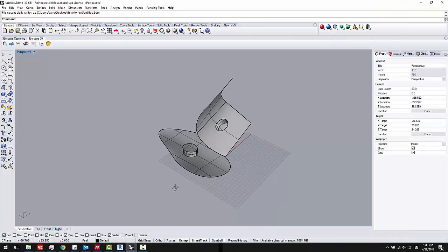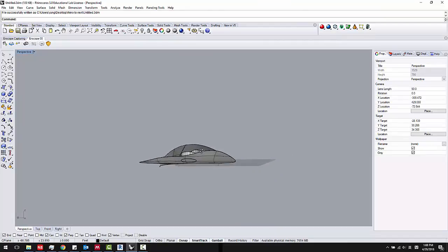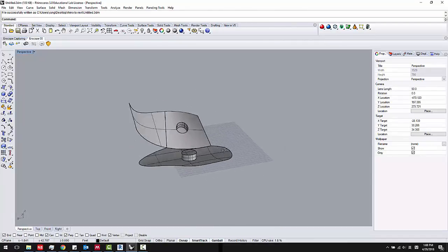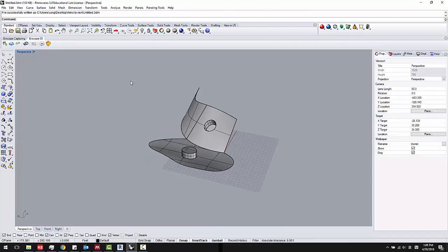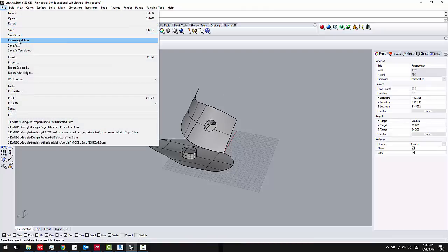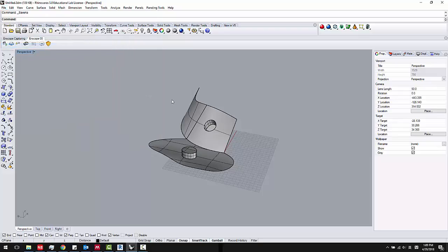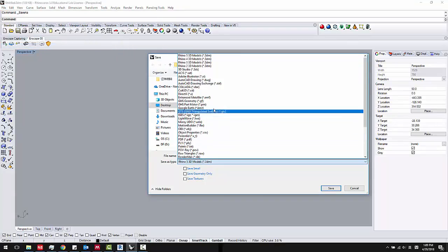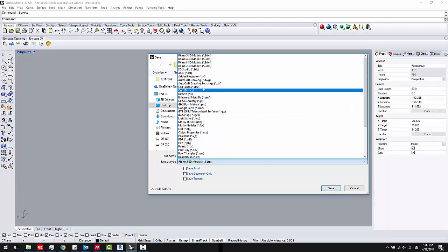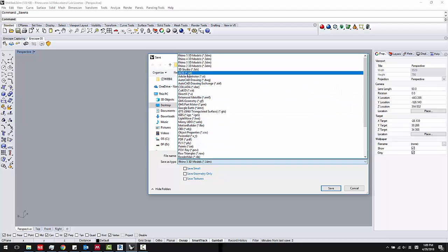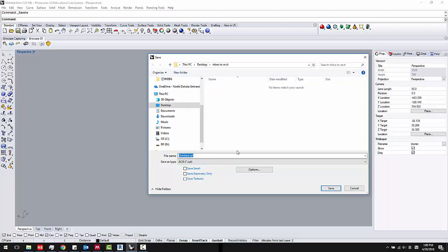However, how we're gonna connect them really well is by using different formats. So you wanna make sure for every project you have a folder and you save them. For example, if you wanna link this to Revit, you wanna save it as this called SAT ACIS.